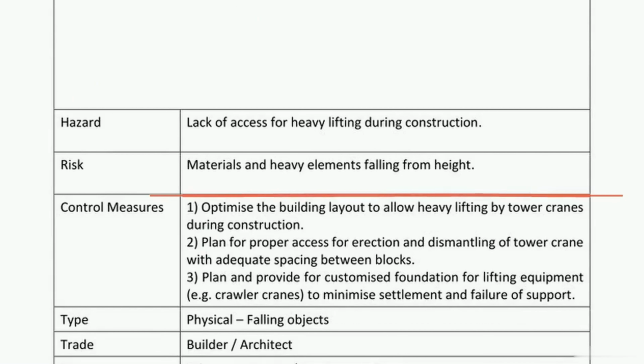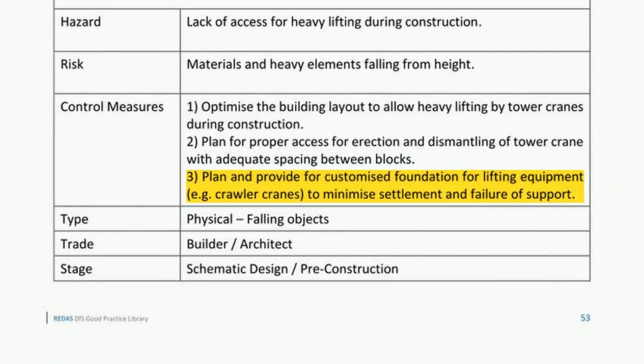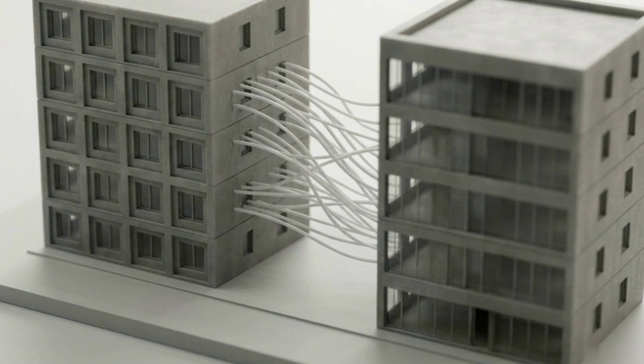Additionally, we see potential for mechanical failure. Without customized foundations for this spacing, crane ground pressure leads to settlement and support failure. Tightly spaced block configurations also introduce environmental hazards by amplifying wind loads, which makes load control increasingly erratic during lifts.